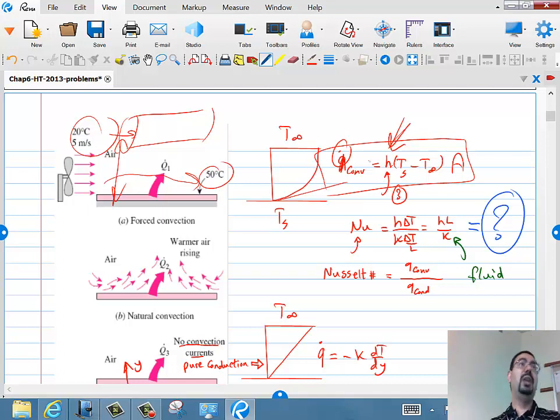All right? Or h delta T, this is going to be watt per meter square. All right? And all those formulas, all those three chapters, is basically just to try to figure out what is the h that will do this magic, that you multiply by delta T, Ts minus T infinity, and that would be the Q getting out. Okay? So, how do they do this?